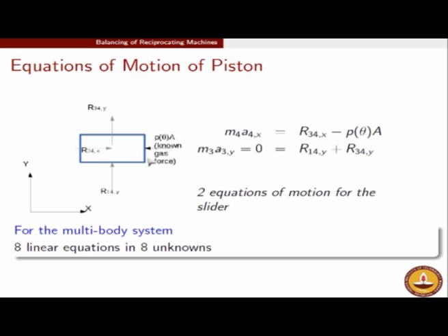But at this point we are assuming that all these forces are passing through the center of mass, and hence the piston is having only a reciprocating motion. Once a body has a translatory motion, then all points in the body have identical motion. I do not need to worry where the center of mass is. The center of mass acceleration is the same as the acceleration of any other point. So the question of the center of mass for the piston is irrelevant, hopefully with the understanding that all the forces are passing through the center of mass.